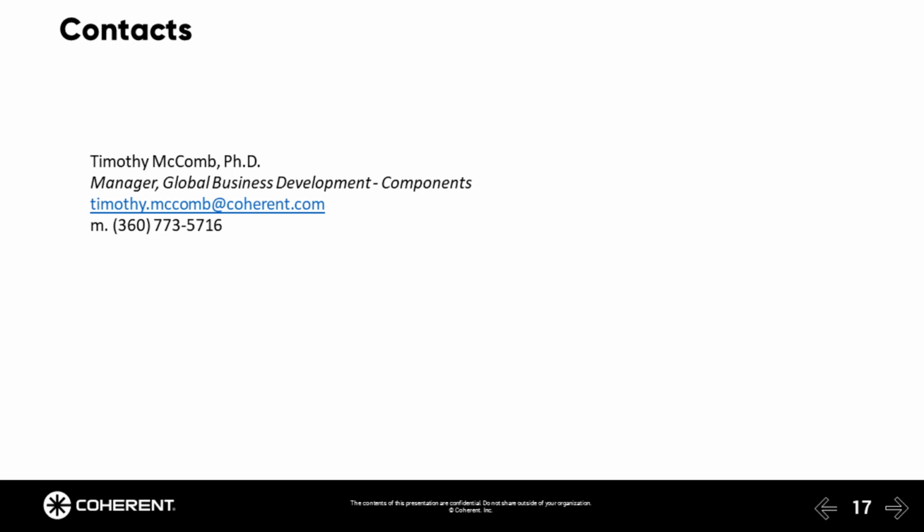Thank you. Next question. What is the highest power your isolators can handle? The highest power our isolators can handle is on the order of 2 kilowatts of average power at 1 micron. That's our hero result at the moment. The standard products are usually rated for just under 500 watts of output at that 1 micron regime. But we're constantly pushing the boundaries, so we'd love to hear if you have new challenges.